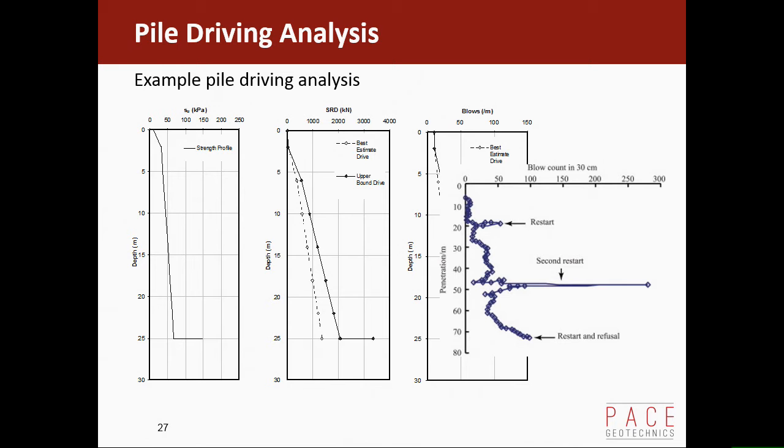I don't know of anybody who's using a vibratory hammer on a regular basis. Just to try and get over a refusal and then carry on? Yeah, it's a different hammer, that's the trouble. And they're not little things. Really? Yes, money and the craneage time. If you pick one up and put it on the pile to get it started, you've got to come back and then put the other hammer back on, so usually you go with one hammer.